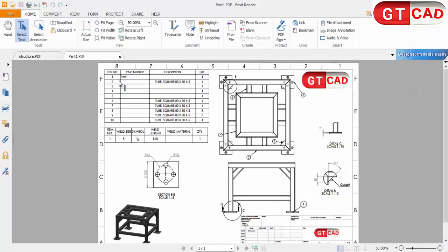Go to the other drawing that describes the profile. Look, all the profiles are 5 millimeters. The type is tube square. Okay, look, I want to select these 8 profiles in a new group, and I want the square profile in number 2.